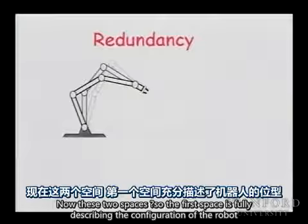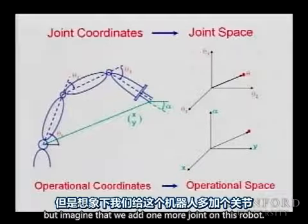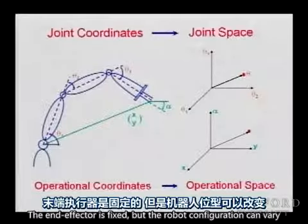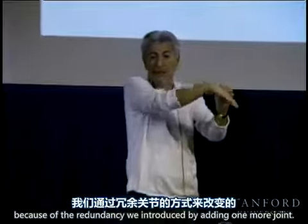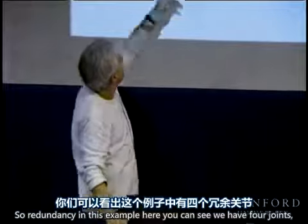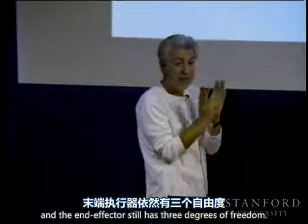Now, these two spaces, the first space is fully describing the configuration of the robot, but imagine that we add one more joint on this robot. The end effector is fixed, but the robot configuration can vary because of the redundancy we introduce by adding one more joint. So redundancy: in this example you can see we have 4 joints, and the end effector still has 3 degrees of freedom.